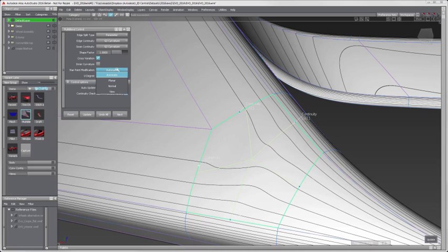Starpoint Modification lets you choose between automatic, which lets Alias choose the best option, and there's no control for the user. Planar, the user moves the star point defined by the plane of the current star point in the normal direction.